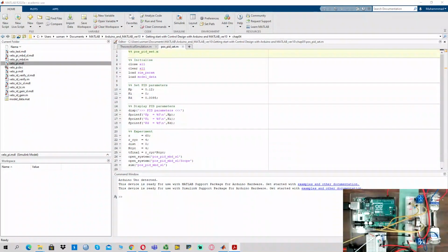One motor is powered and one we are using as a tachometer, as a sensor, and at the output you see there is a low pass filter right here. The low pass filter is responsible for suppressing the noise from the motor as much as it can, to give a better reading at the A0 input of the Arduino.